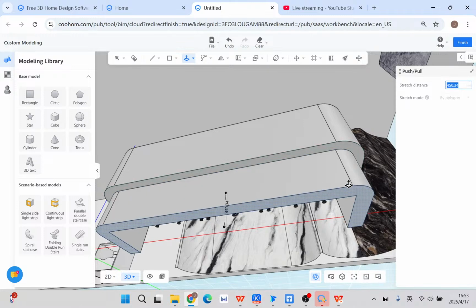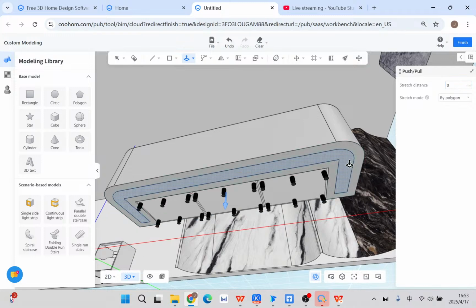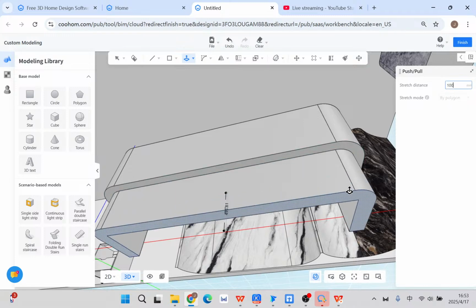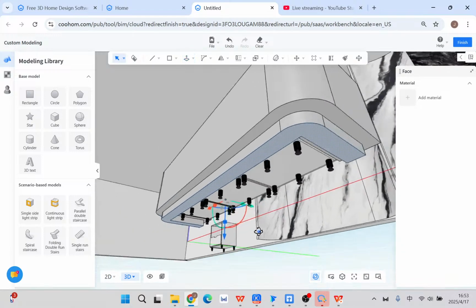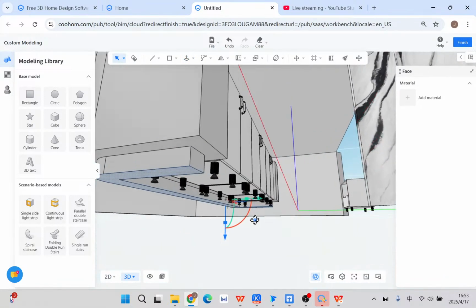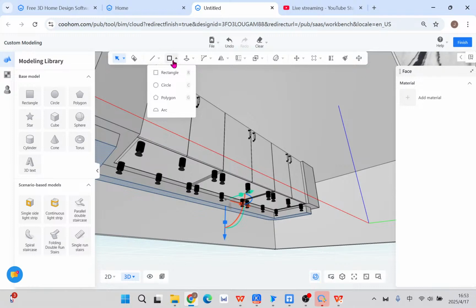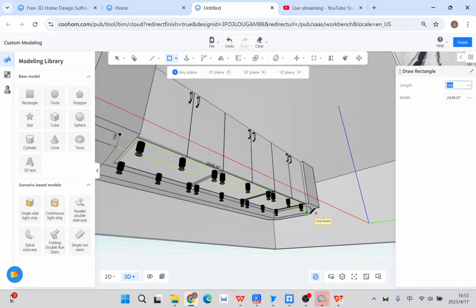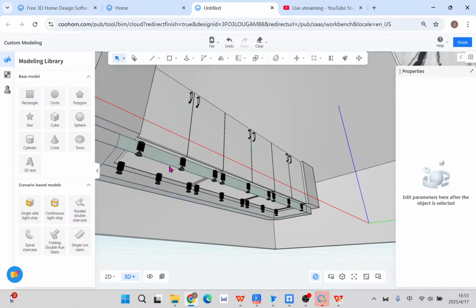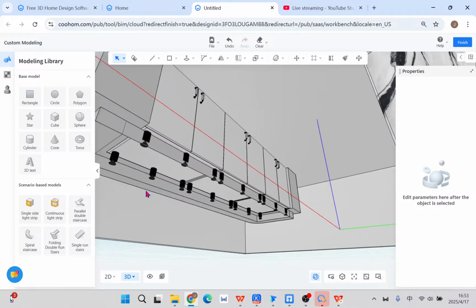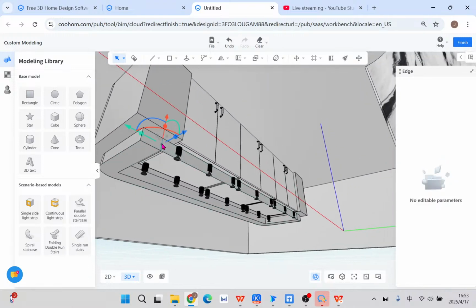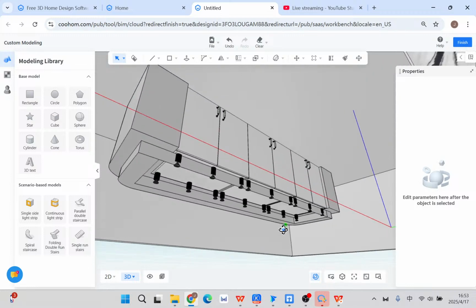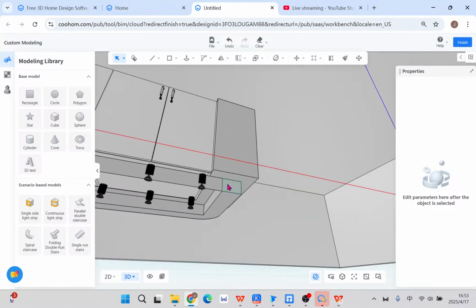So first you finish the outer area, and for the inner, you don't need to draw it again. You just need to use the line to turn this angle back. If you want, you can delete the duplicate line, the shape that is duplicated.